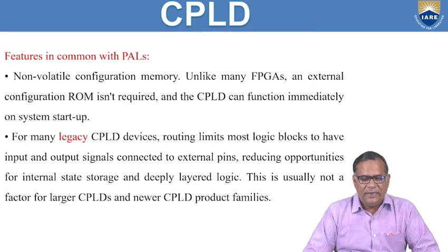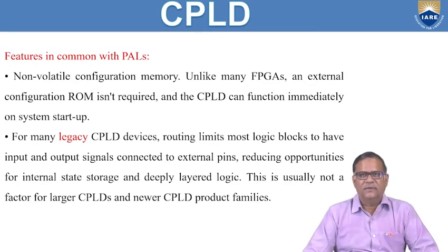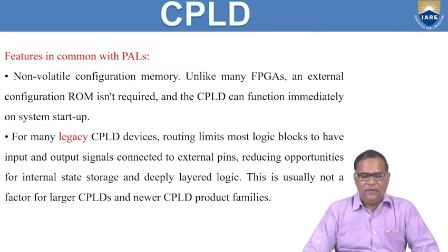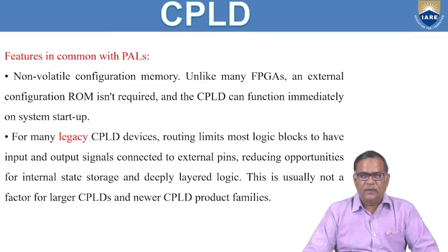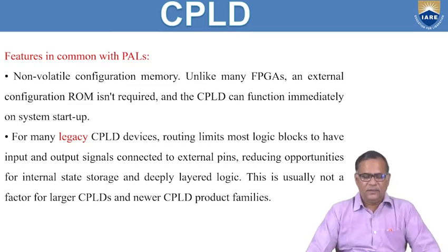And for many legacy CPLD devices, routing constraints limit most logic blocks to have input-output signals connected to external pins, reducing the opportunity for internal data storage and deeply layered logic. So this is usually not a factor for other CPLDs.